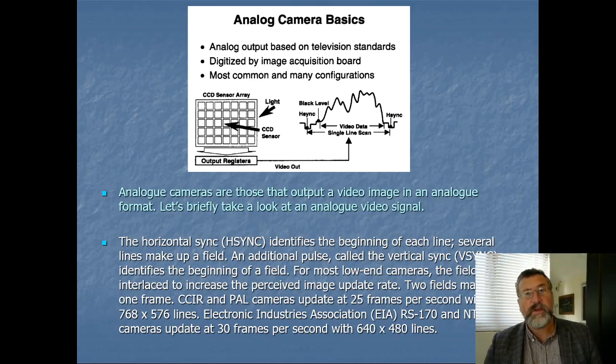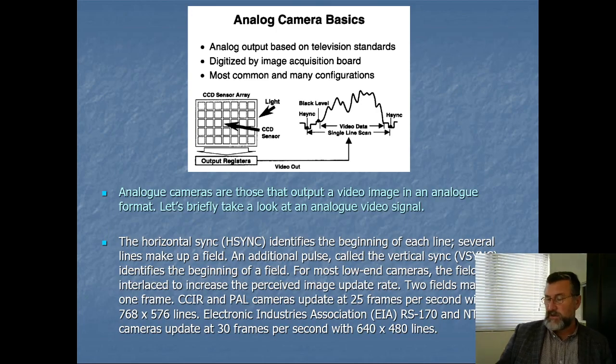Years ago, it used to be a bit complicated, just as a little bit of historical interest. We used to have analog cameras, which is a bit crazy, where we had a CCD producing a digital image, then convert that to an analog TV standard, then have an analog to digital converter in the frame grabber and convert it back, which was a bit crazy because you lost resolution, you got noise, so it wasn't a good idea, really. We used to have TV standards, of course, in the UK it was PAL, in the States NTSC.